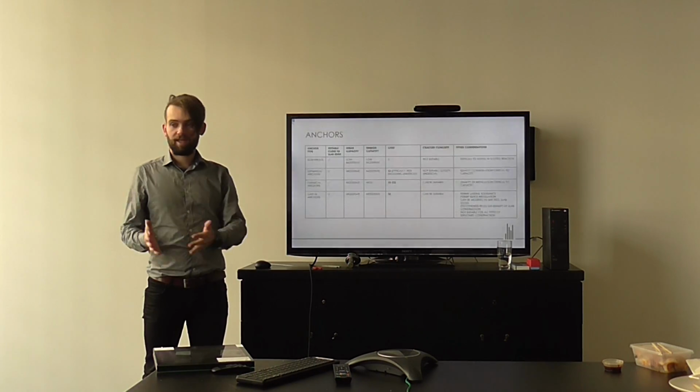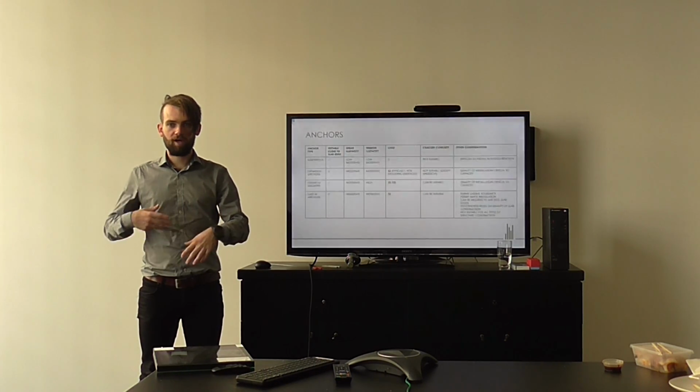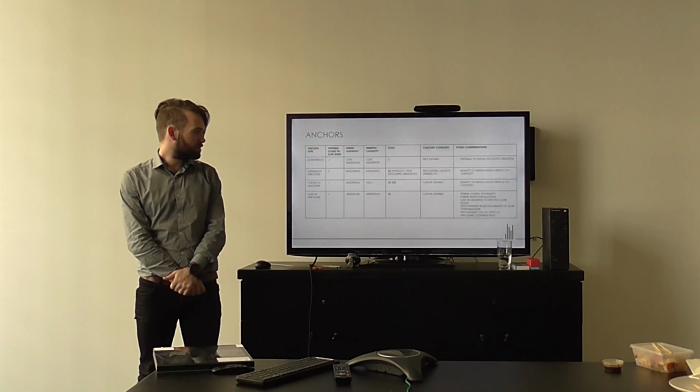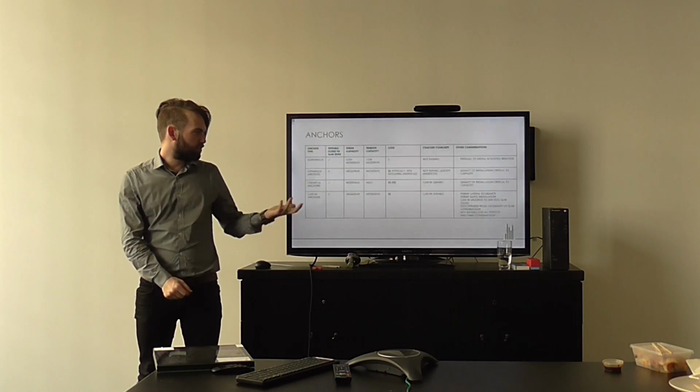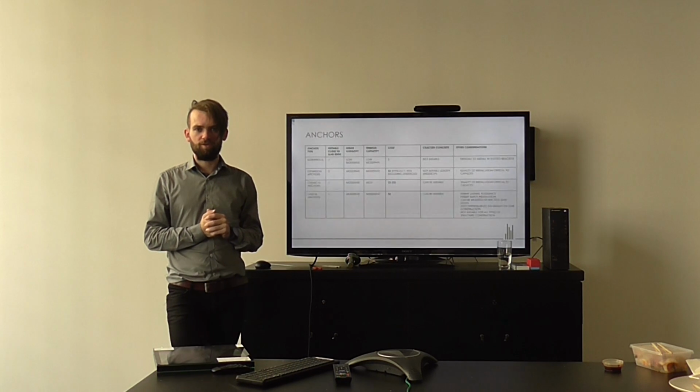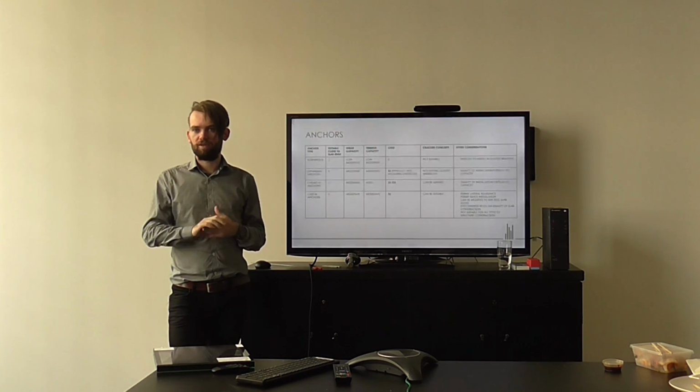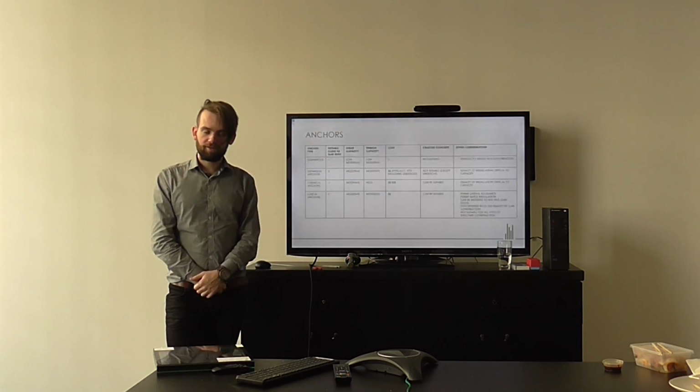And then casting anchors, there are probably a few here at the bottom. Some good ones, they allow that tolerance we spoke about before. They are pretty quick when you're installing panels, and they can also be modified to suit different applications. You can remove the legs and weld them to steel and so on, so they're pretty useful.